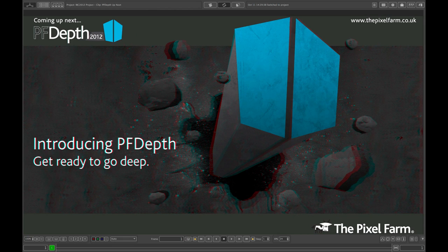Now before we get too deep into it, I just want to explain the difference between PFDepth and how most facilities are currently doing stereo conversion work. Typically what gets done is a lot of rotoscoping. You might be using Mocha or Silhouette to create a bunch of detailed rotoshapes that represent objects in the scene, export those out to a 3D compositor like Nuke or Flame, and then you apply an arbitrary gray value to that shape. The darker it is, the further back in the scene it will be, the brighter it is, the more forward. The problem with that is that there's no real relationship between that value and the actual world space of the scene, let alone the camera's position.